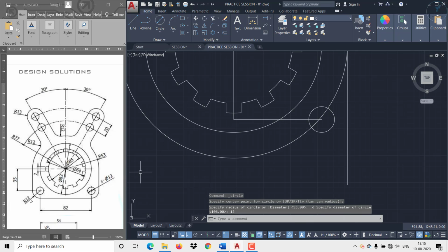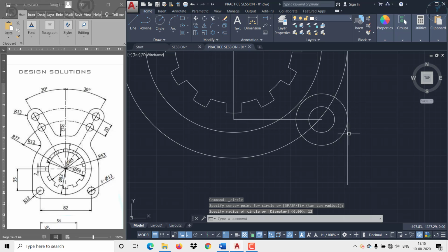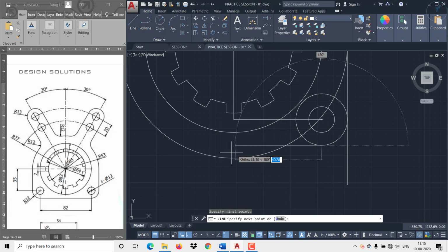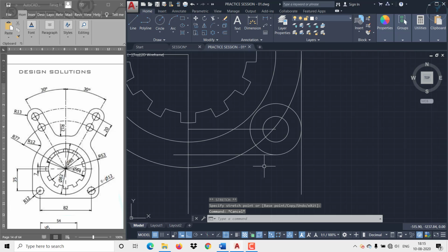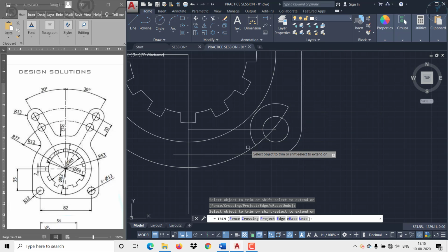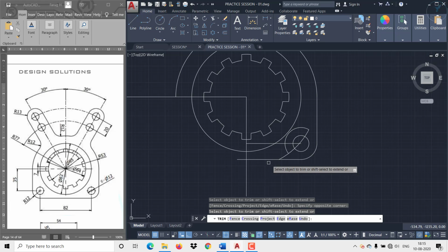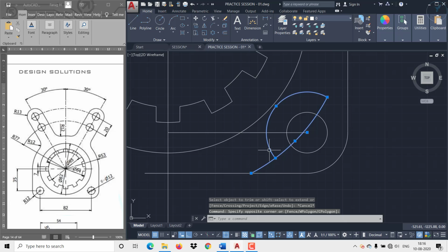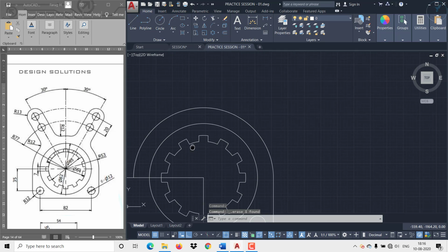On the same center we need to make radius 12. So where it has ended, just from that quadrant, make it straight. So now I'm just making this line as a origin line like this. So the extra parts we can trim it off. So this we don't require. This. So these things you can delete it like this. Now either you can extend this as well.